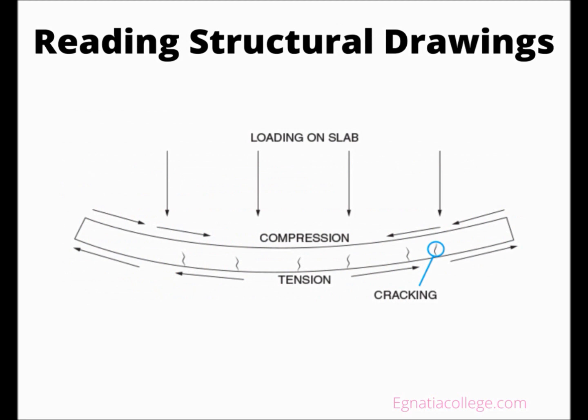Reading structural drawings. The structural drawings for Urban Courts that are included in your packet are 2 plan sheets, S7.1 and S7.2, and 2 sheets of details, SD1 and SD3. Familiarize yourself with the various views, schedules, and notes and how they are referenced in the plans. Note that most details on S7.1 will be found on SD1, and most details on S7.2 will be found on SD3.